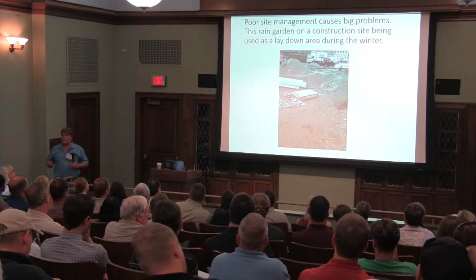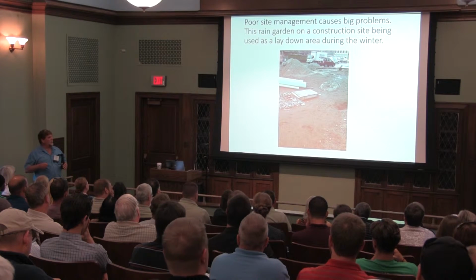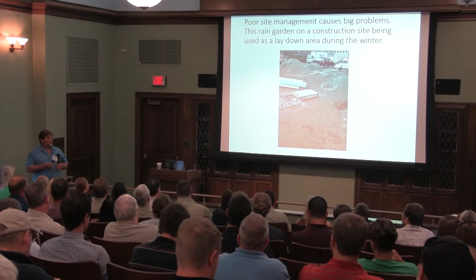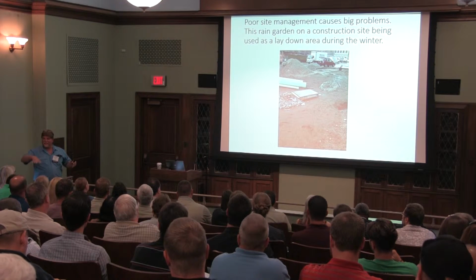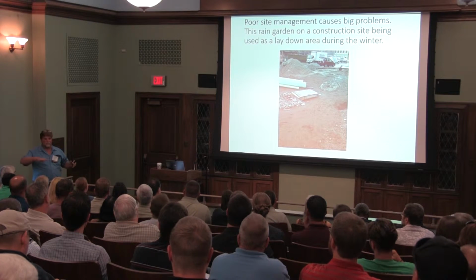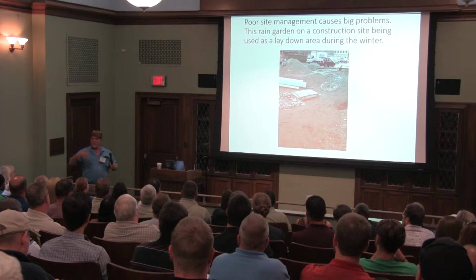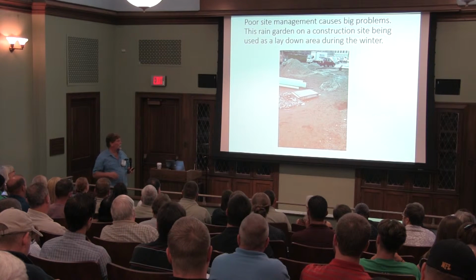So from a maintenance standpoint, what's the point when you have a rain garden that's not performing properly, holding water? One of the first things you want to do is go out there and take a shovel and dig a few holes in this thing, rough it up. One of the great things about planting with all those plugs is you're actually turning all the soil up, getting that little bit of a lens, potential lens, broken.